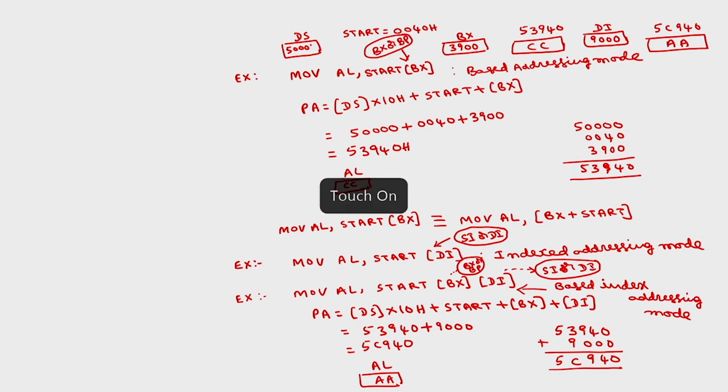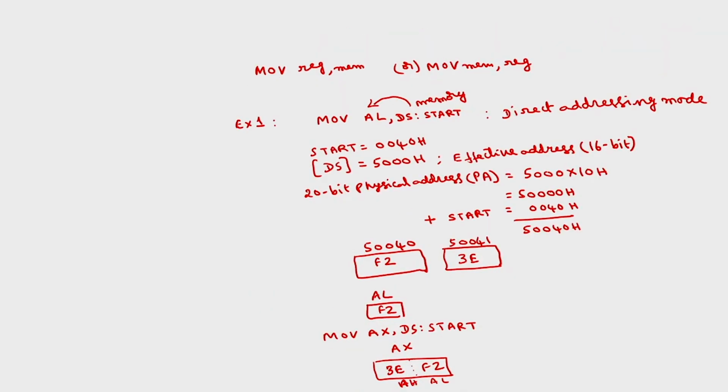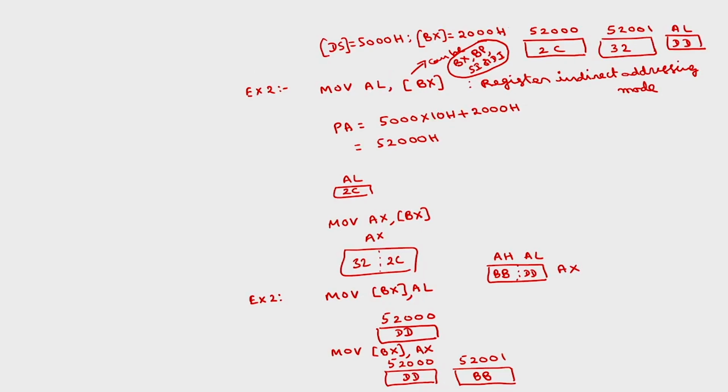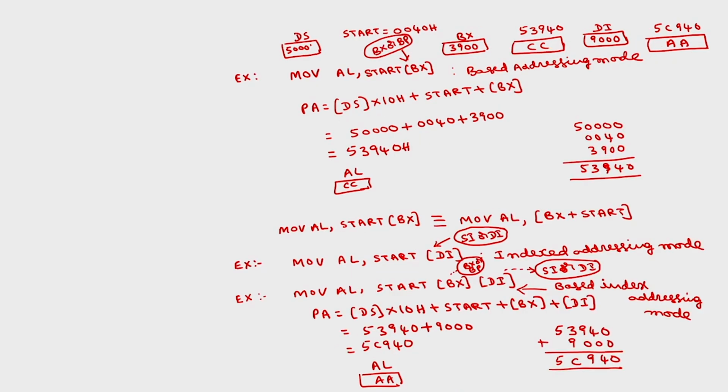We can compute using only the data segment that is given here, then add some offset, or we can compute using base registers or index registers: only base register and displacement, index register plus displacement, base register plus index register plus displacement. This is to compute the physical address of the memory, and the register will be specified in the instruction. Register can be either 8 bit or 16 bit. So, these are all about the move instructions, and we can have move string operation also.